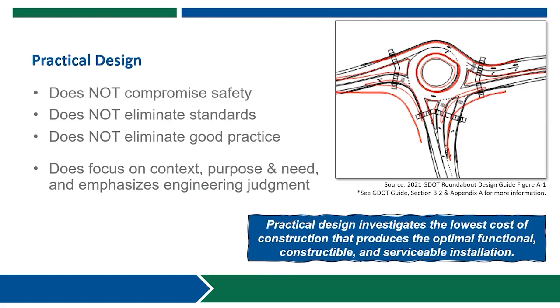They determined that one bypass lane, the eastbound right turn bypass, was not required. They were able to revise the geometry for the northbound right turn bypass, and as you can see, if you review the appendix, they were able to reduce the overall footprint of the roundabout without negatively impacting the performance goals, the operation and safety of the proposed roundabout. And in fact, in a lot of ways, they've improved upon the original design.